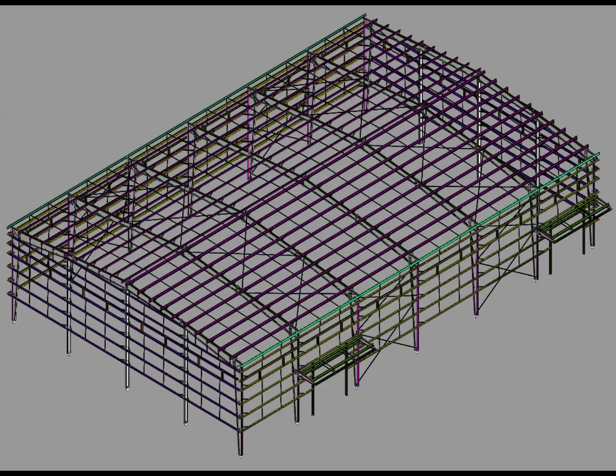First, identify the member in the drawing. Then locate its position in the framing. Then locate the same member in the 3D model. And finally, inspect the connection and surrounding members. This four-step approach is very useful for anyone learning PEB modeling.